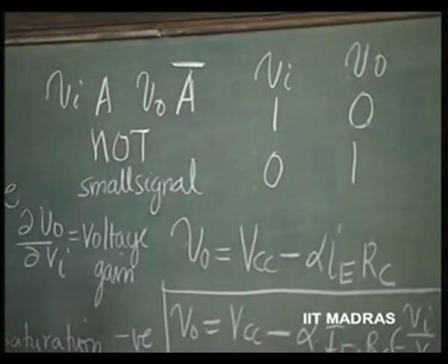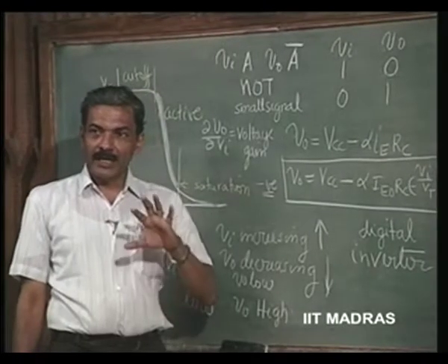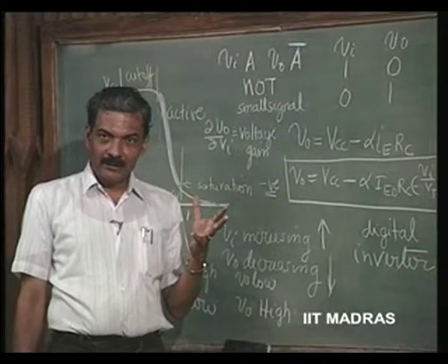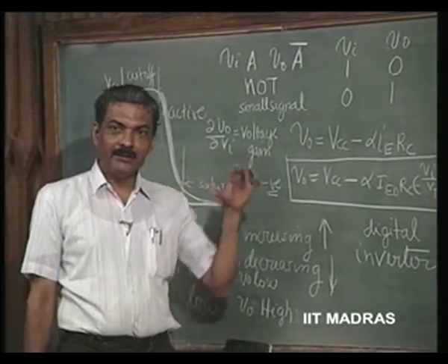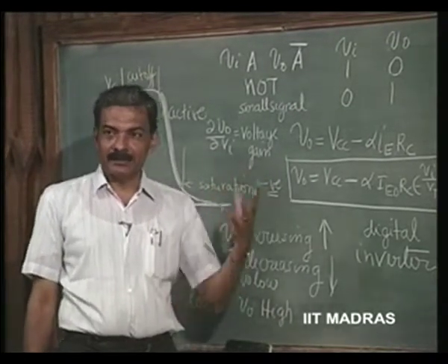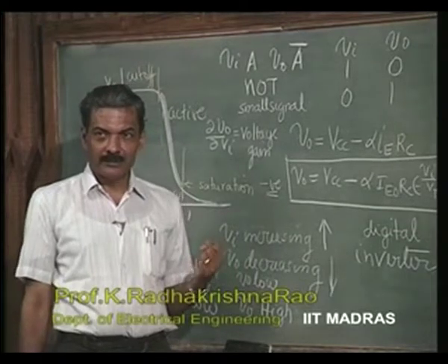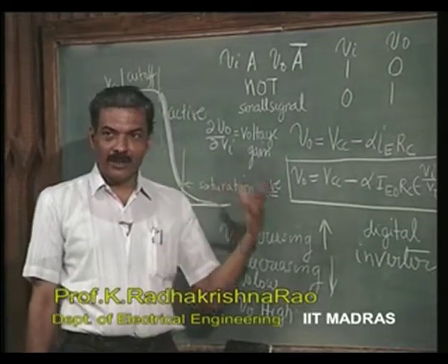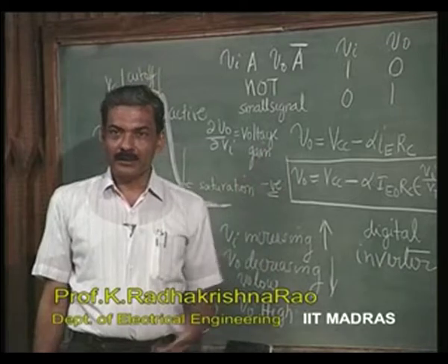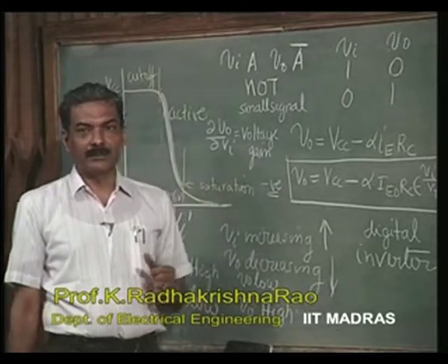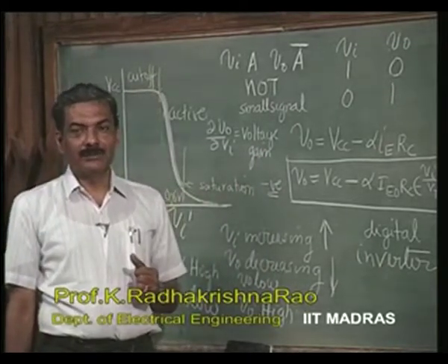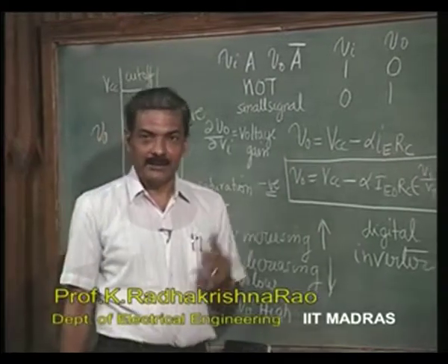With this NOT operation added, we can have AND gate cascaded to NOT operation forming NAND gate, OR gate cascaded to NOT operation giving NOR gate. NAND and NOR gates by themselves can give you design of any digital system.